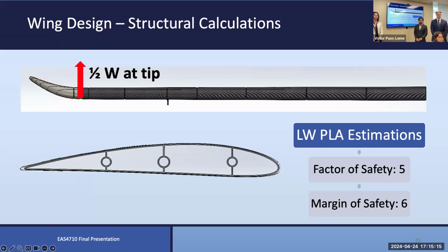I consider that's okay, but as engineers we always want a calculation closer to reality, right? And something closer to reality is the elliptical distribution. In your graph, the green line, you already showed me your elliptical distribution. If you already have it, why don't you just use that instead of using half weight, right?